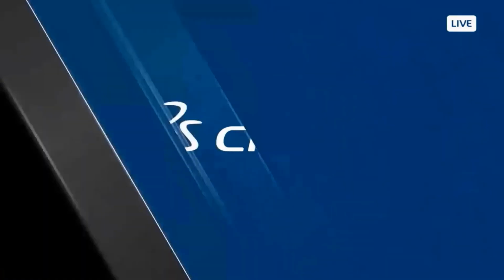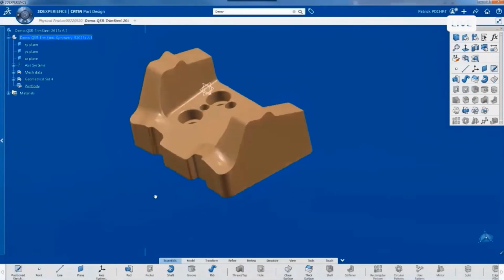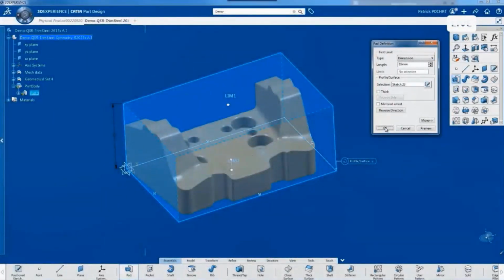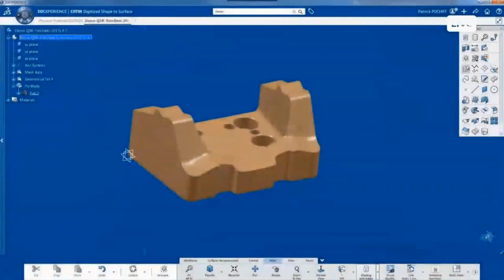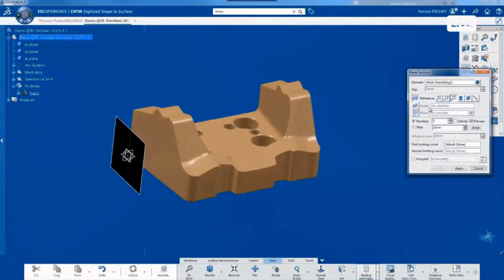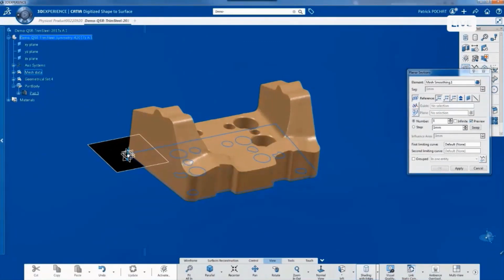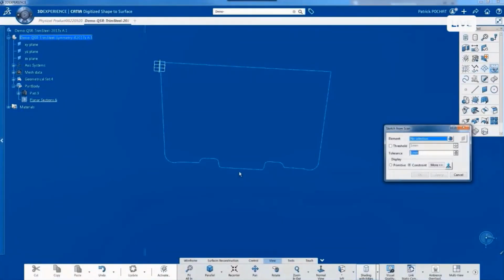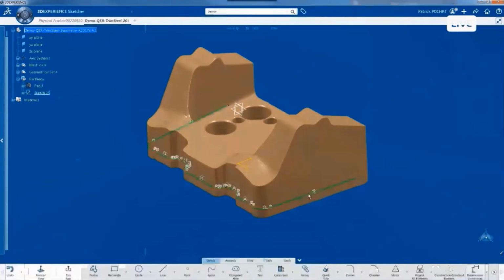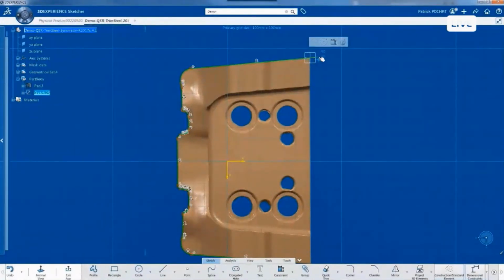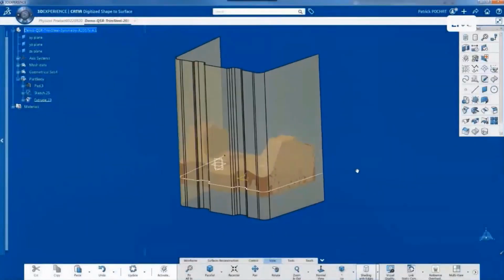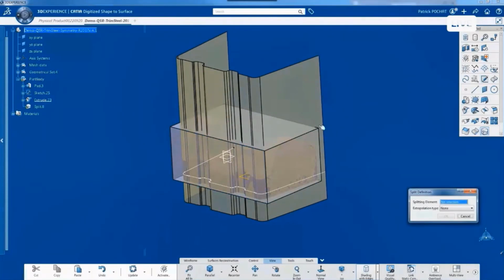For example, you scan the tool, you import the STL file in CATIA. Here, we will recreate a solid box exceeding the part size, and we will enrich the box little by little, like here, creating, for example, sections on the mesh, approximating later on this section into segments, arcs and ellipses. The result is a fully constrained sketch that you can edit and complete manually, like here, extrude it with standard extrusion functions, and refine the box you previously created.